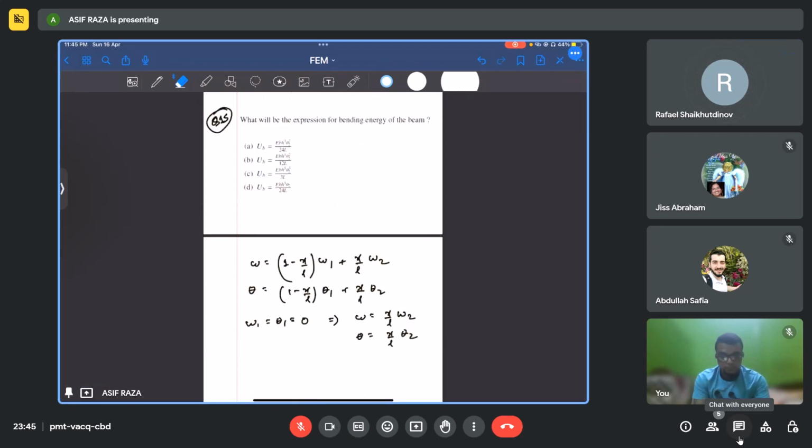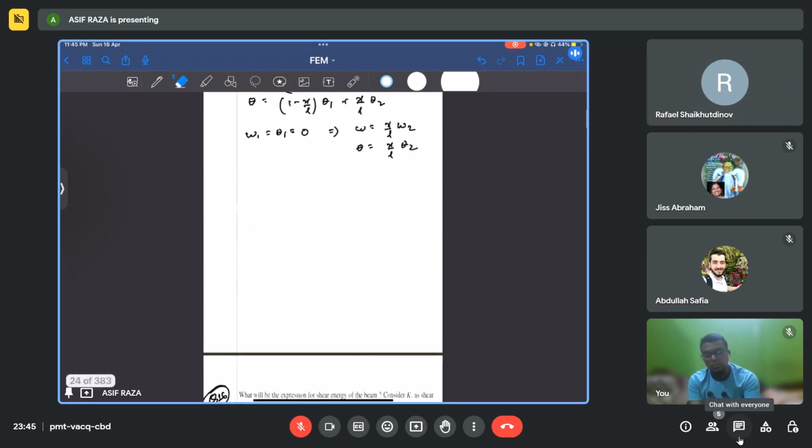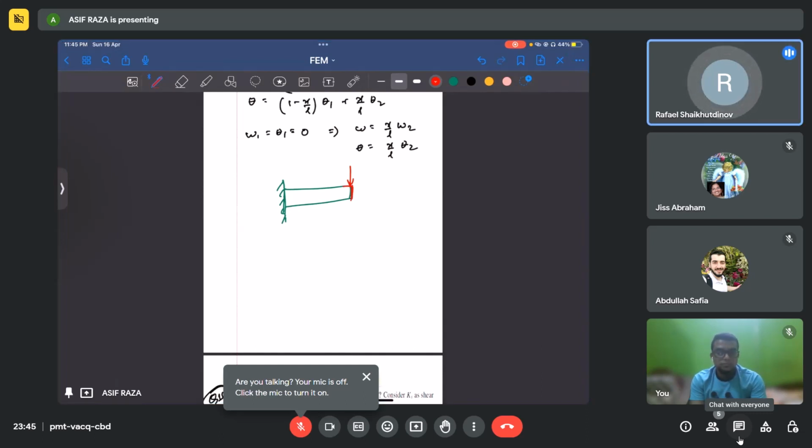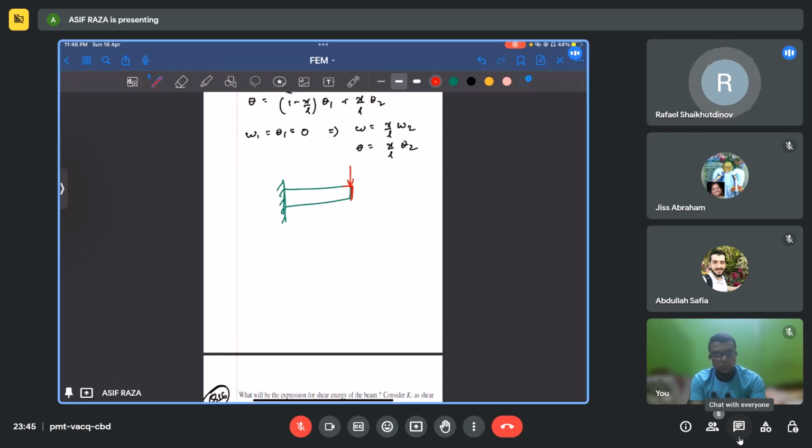Actually, if you see, there is a question. There is one more thing. It depends on, if you are applying a point load here, is it at the top surface or at this surface? In theory of elasticity, the boundary condition for this P is the integral of tau along the surface equal to zero. That is also one thing you need to see.